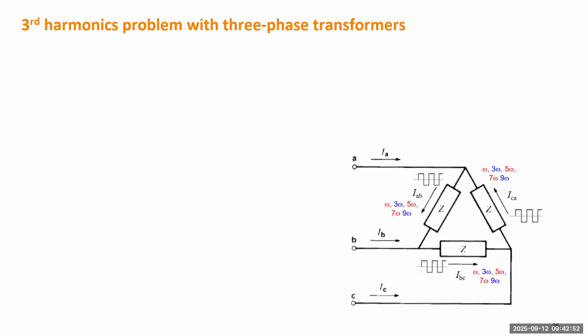But this is too high, so usually we can ignore it. You don't have to consider very high order harmonics, because the higher the order, the smaller the magnitude. So you can stop somewhere. Usually 5 or 7 should be enough. Third order harmonic is still significant.